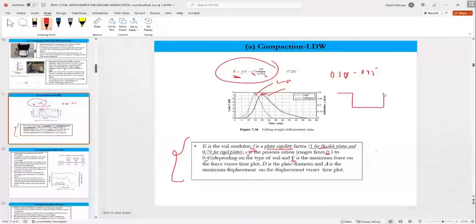If I had a trench like that and I was going to put my foot in here, and it is very loose soil, I would just cut back this and densify this to minimize settlement.